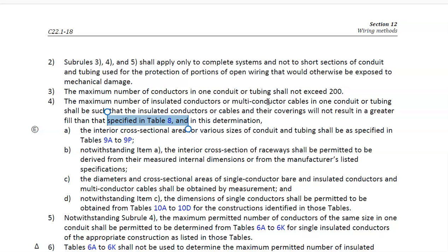All right, voltage rating. Do finish those examples that are inside of there. Voltage rating, there's going to be different voltage ratings associated with different types of cables. We went over that inside of your table D1. If I don't know how many volts I can have on a piece of cable, I'm going to check it inside of table D1.